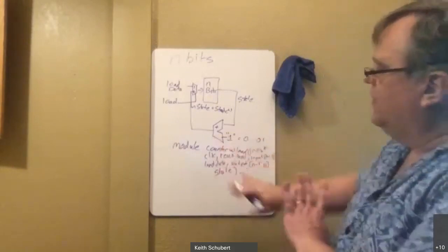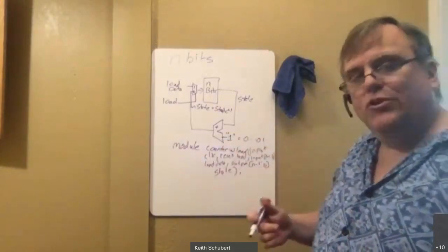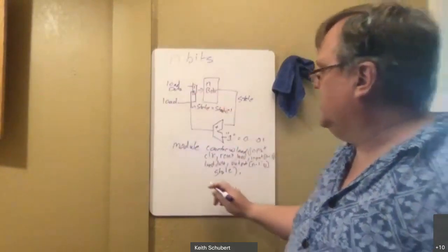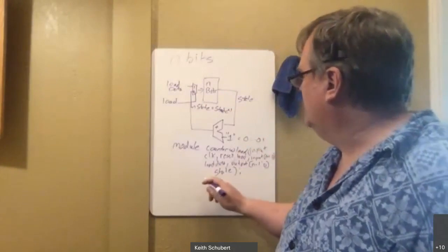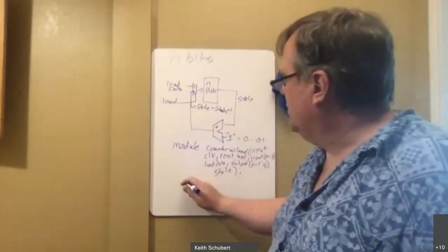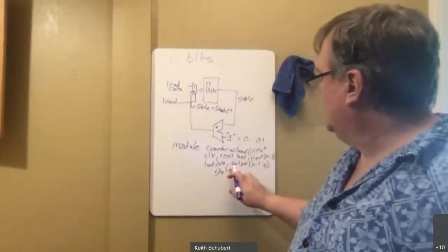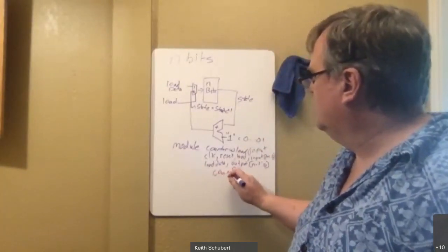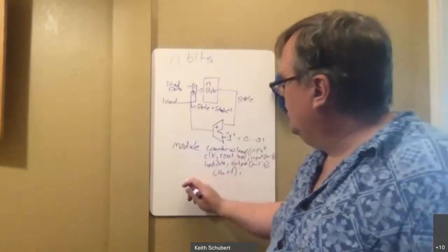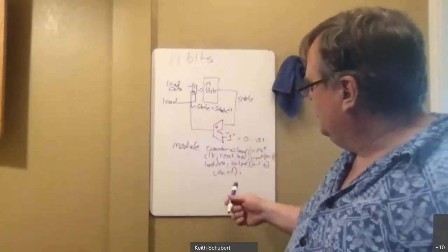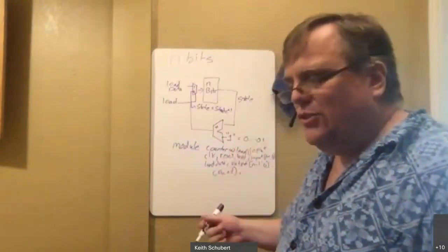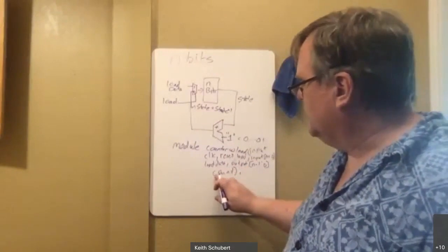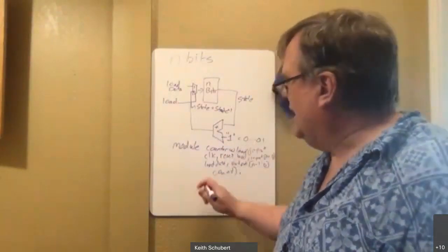Right. So I could set up my module. I'm going to need basically these state bits here, where I've got my state output. Actually, let me call this count, because I like to do state completely internal. Depending on the version of Vivado, they sometimes let outputs be accessible, sometimes not. The standard is not to.